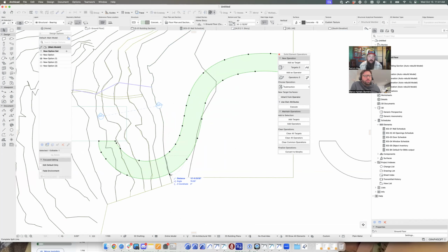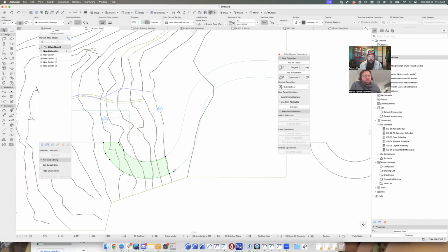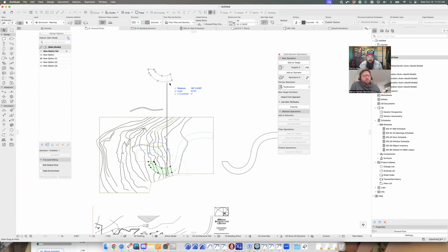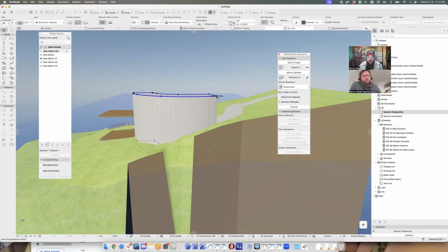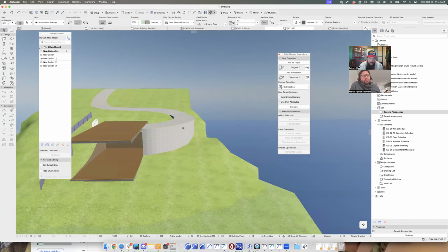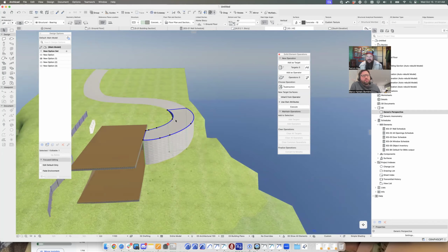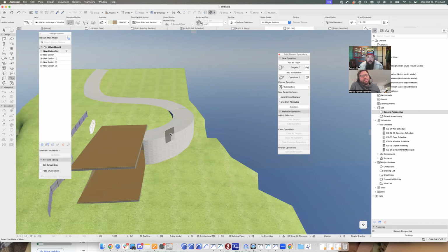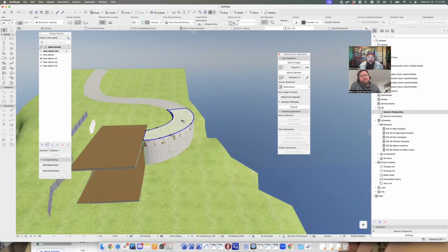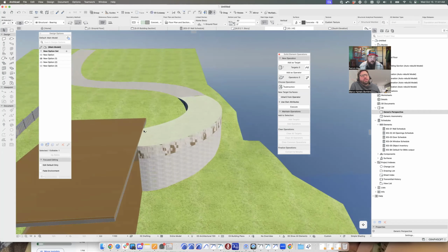We're going to follow the contour to this point. Now I'm going to take this piece right here. Since this is a slab, it's probably not going to play nicely. If we look here, that piece goes right there, and technically we could pull that down to right there, and that happens to actually line up. But if I needed to have any other slope, I could not do that with a slab. So I would have to replace that slab with a mesh so that I could feather this node to wherever it needs to go.